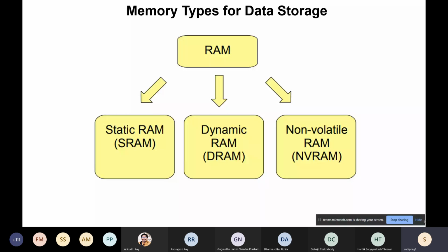If you store something in DRAM and then forget to replenish the charge, it will forget the data. I repeat, what I mean may be confusing. I have one transistor and one capacitor in a DRAM. Think of one transistor in source follower mode. Remember source follower mode from analog. Source follower mode means the drain of the n-channel transistor is connected to VDD and the source of the n-channel transistor is driving the load, resistor or capacitor. Here the load is a capacitor.